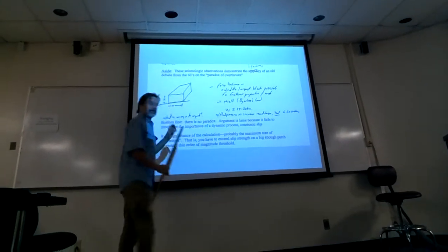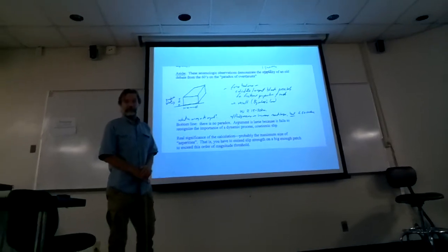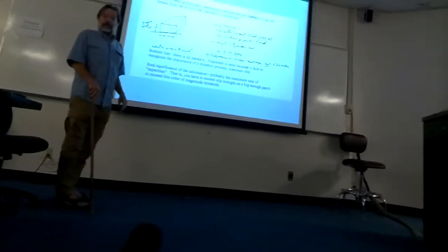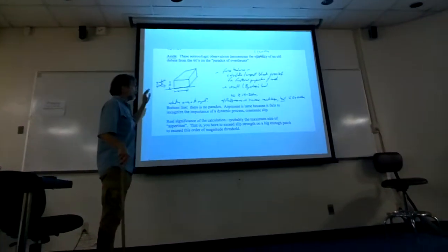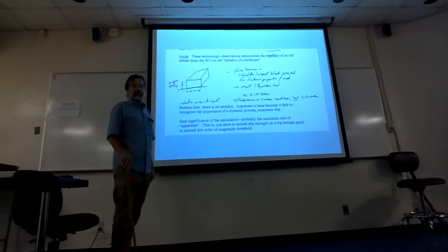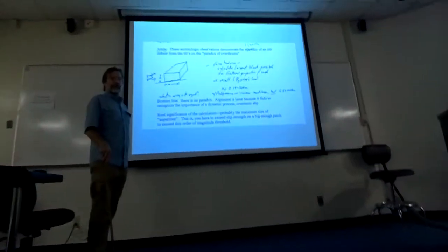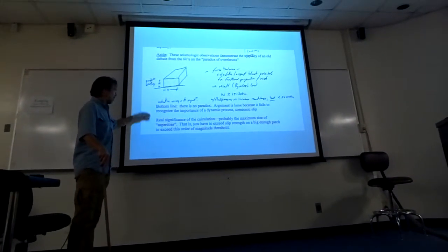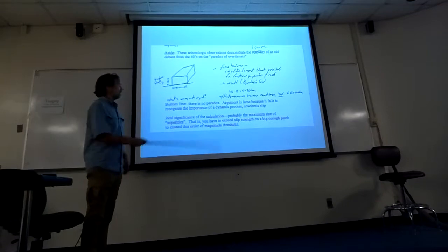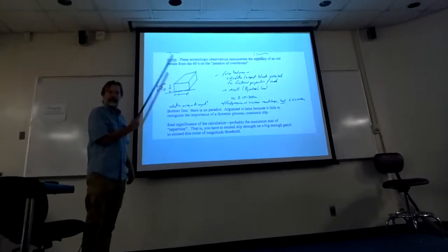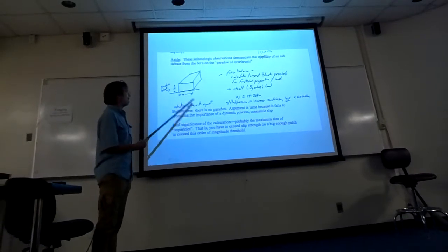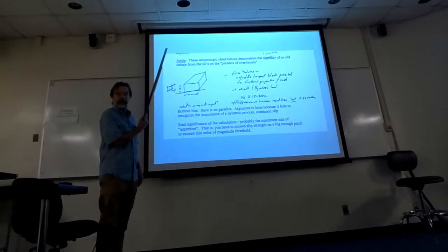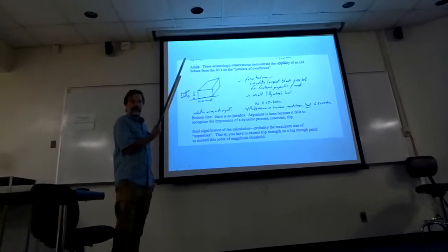That's what people thought in the 1950s was the solution to the paradox. But it turns out there is no paradox, because the problem is formulated wrong. It's formulated in the context of static friction. The moment you consider the problem in the context of asperities and breaking asperities, this is a lame calculation, because it has no bearing on the problem. The only thing it may tell you something about might be the size of asperities. They have to be broken to make the material slip.